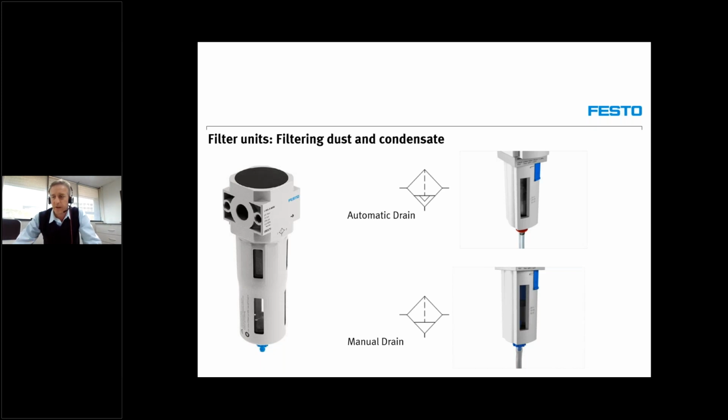Not a problem. No, I said very often we ask to quote on both options from the sales perspective. So for both the mechanical, the manual drain and the automatic drain. But we know from experience that a lot of people have the very best intentions at heart, and so they do have a regular service plan or maintenance plan in place, but invariably it isn't maintained like that. So don't you think that by default, automatic drain should almost be the standard option?